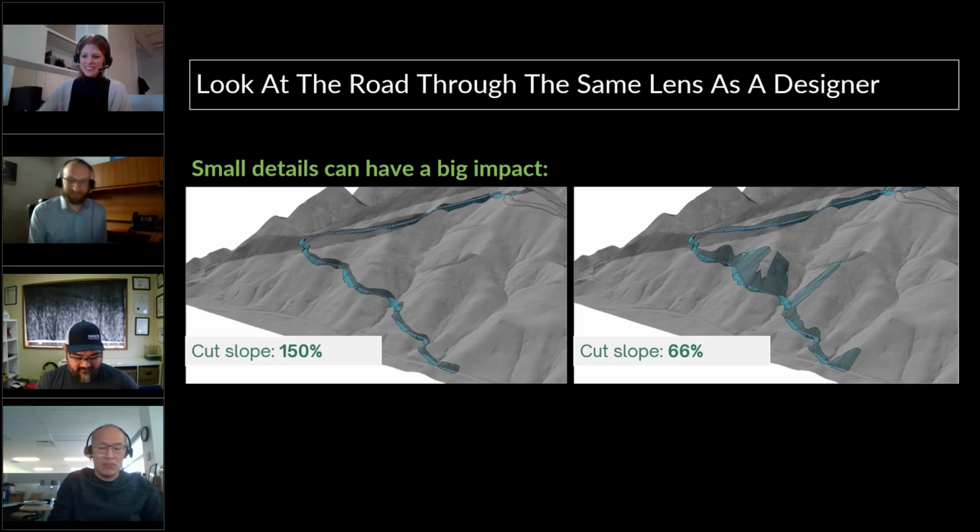All right. So you can bring in a shapefile. You can also bring in LandXMLs if you can get them, if you're talking about bringing in alignments. The practical limitation, on the techie side of things, is that a shapefile is going to be a polyline, so your curves aren't true curves.